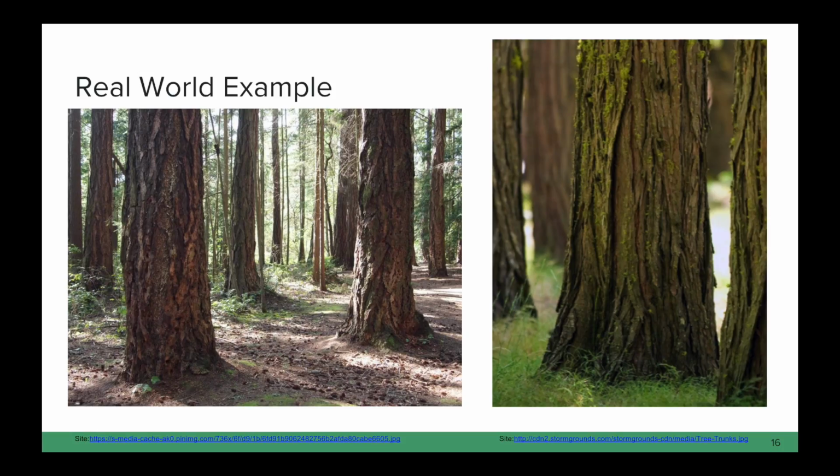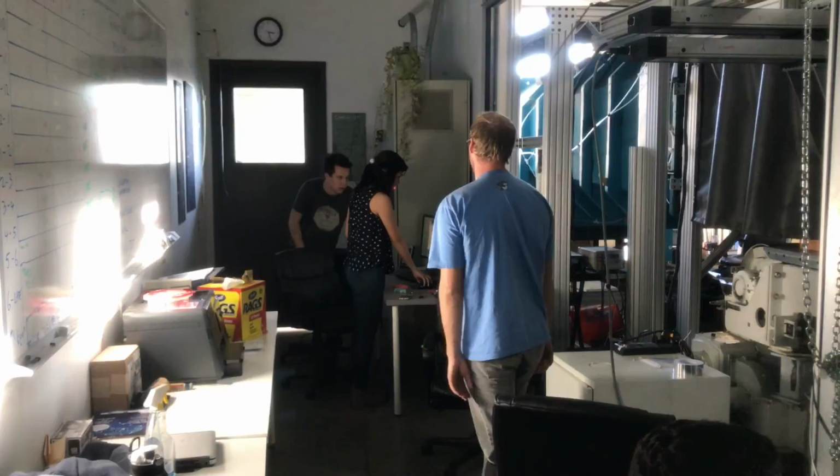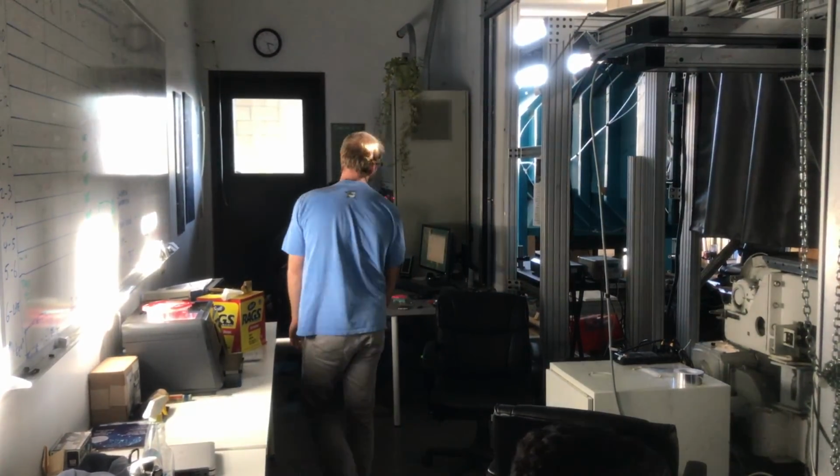Cylinders are everywhere in nature and in man-made objects. The most common example to mention is the trunk of a tree. This is roughly the shape of a cylinder and has to counteract the drag force caused by wind, especially when the tree is tall. Trees are able to trip the boundary layer of the flow by making the surface of the trunk rough, using bark. In doing this, the boundary layer is tripped and the flow stays attached to the trunk for a longer period of time. It is the same concept as adding sandpaper to the cylinder in the wind tunnel. By implementing this, trees need less grounding force to keep them upright and can create less massive root systems, saving valuable energy.